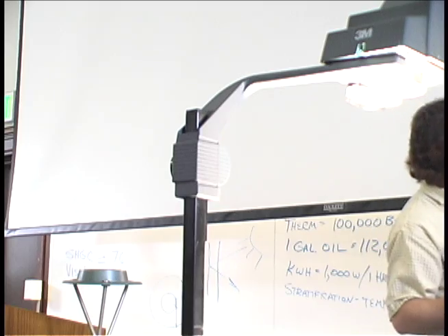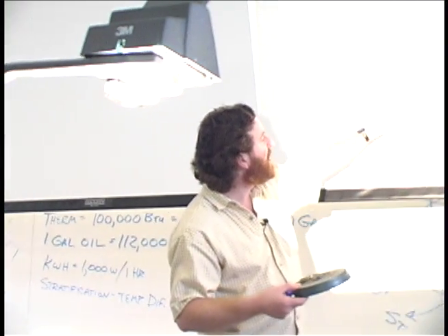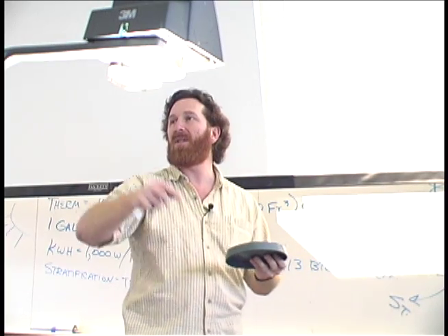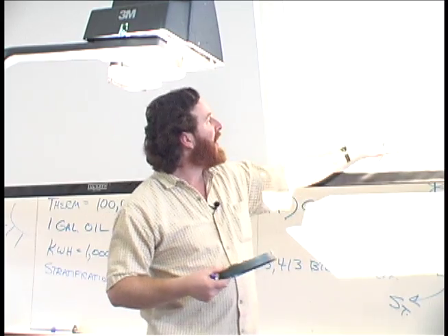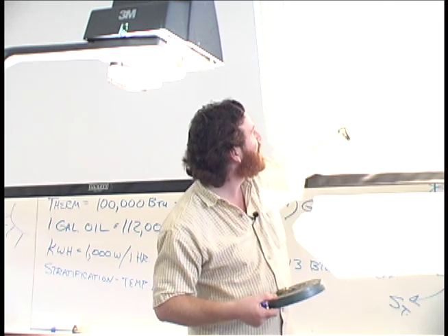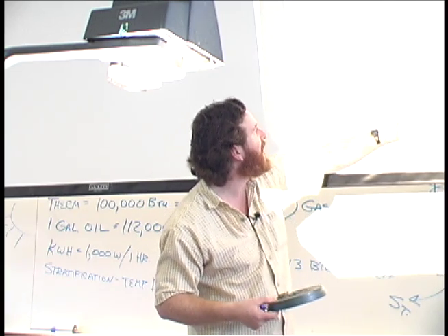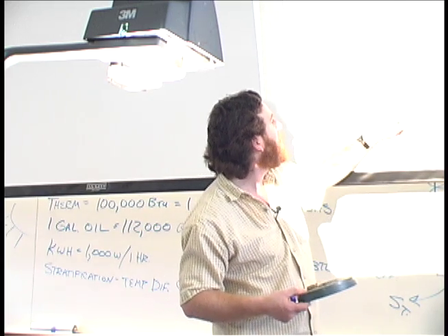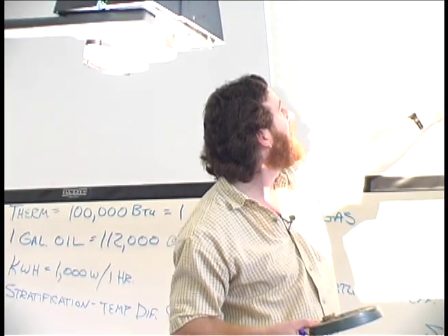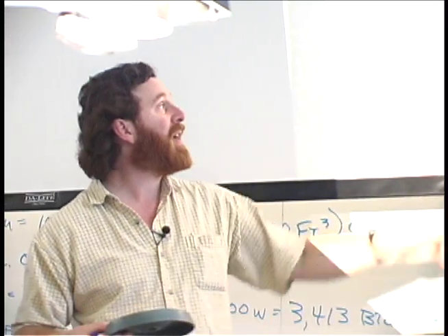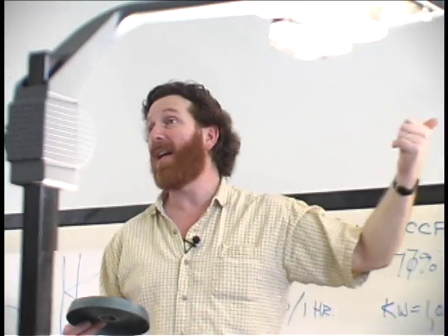But what this does is you've traced your obstructions on here. This is a big conifer tree, so normally I'd put a C here for coniferous. I would show branches if it was a deciduous tree. You can see that this thing is blocking the sun in December and January from about, we're not concerned about before 9 o'clock, so we'll say from 9 o'clock until 10:30 in December and January. By the time you get up here into February, it's blocking from about 9:15 until, say, 10:15. So you're losing about an hour out of 6. And once you're up here into March and September, you're clear. So for a PV system, this is a great solar site.